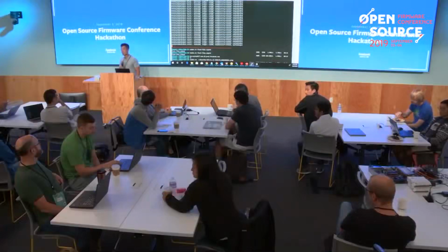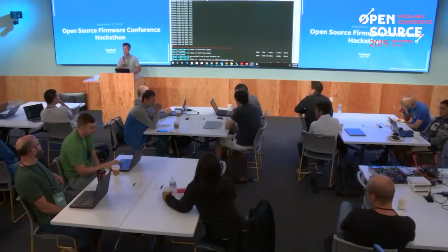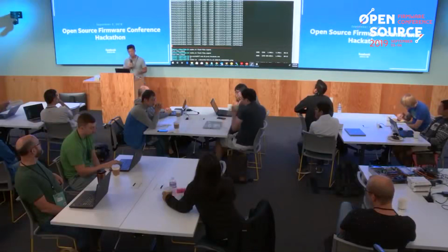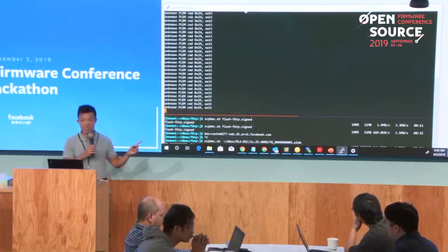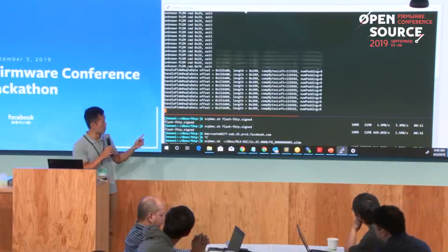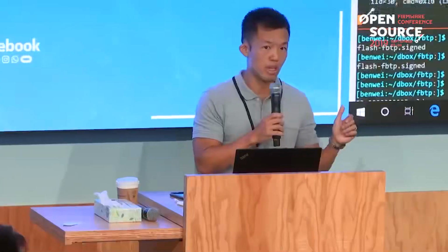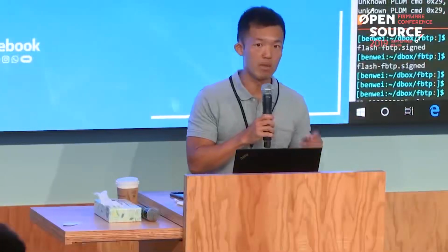After apply, BMC sends a cancel. Yeah, that's a good point. So the question is, what happens after we hit apply and the BMC hits cancel? Actually, that's what I'm doing right now. Because I'm updating a test firmware, it should be almost done. If we do cancel, as long as we don't activate, the new firmware doesn't take effect. So you can actually cancel any time before we hit the activation stage. That's what happened here.